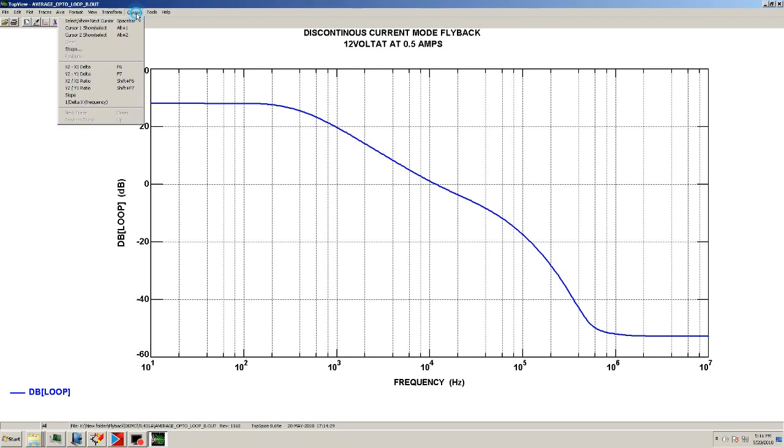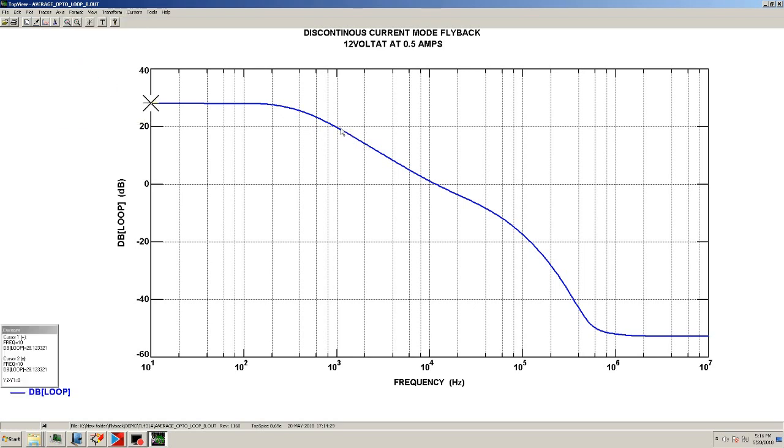Okay, so now we're going to measure the delta, and it's 1 dB. I'm sorry, it's 20 dB per decade. So this is 1 decade apart, and if you look in here, it's 18, so it's close to 20. So this is showing that this has a slope of 20.